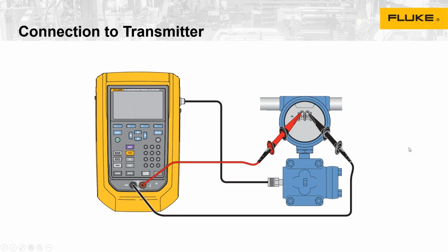Now, jumping across, we wanted to give a good illustration of what a 729 would do. So in a 729 scenario, we'd obviously be doing pressure. The 729 is an automatic pressure documenting calibrator. So this is a pressure-only version of the 754 DPC. It has a built-in electric pump and electric regulator that allows you to dial in a pressure setting of up to 300 psi, and the device will pump up to that and hold. We can do multi-step 3 to 5 point checks, and it will step to each level with that regulator and pressure gauge.